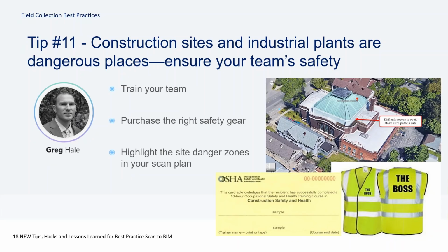Greg, number 11, to continue down the safety theme. Yeah, just a couple more things to add on to the safety list here. So train the team. Again, I've seen a lot more people coming into the industry that aren't necessarily used to the safety standards. So get them OSHA trained, get them a 10-hour certification. Contracting firms are used to more like the 30 or 40-hour safety training, but there's a lot of exposures on project sites that can really provide dangerous situations for your employees as well as others. So it really helps to invest in that and understand you are on construction sites in a lot of cases.